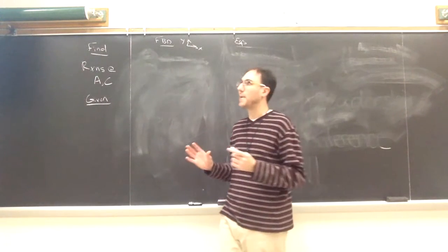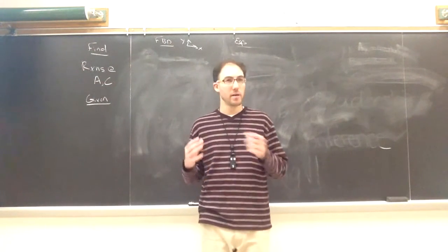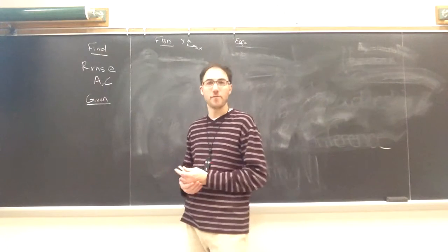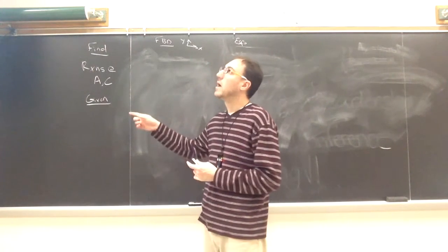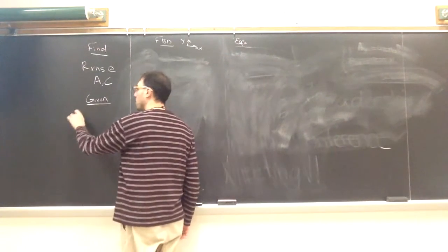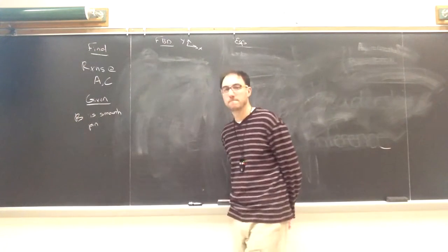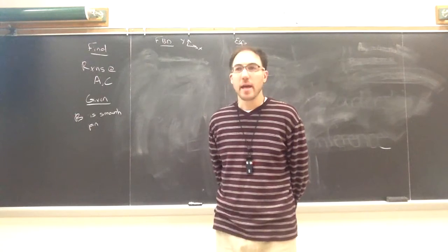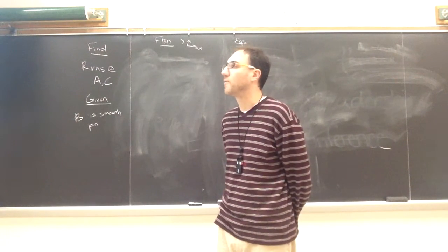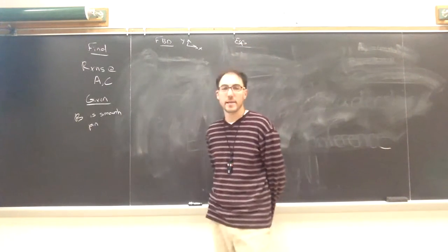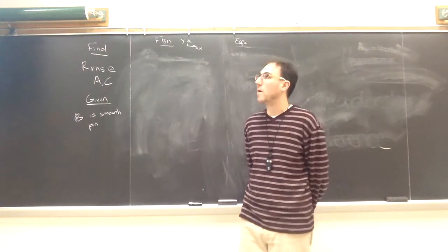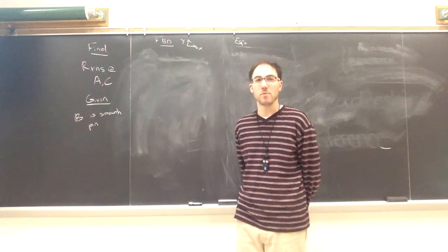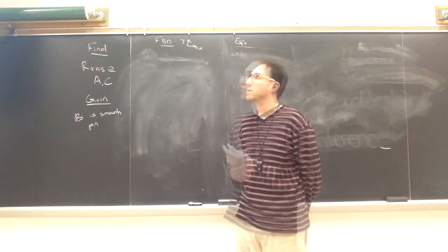So the external free body diagram would only give us 3 equations, not enough for all of the reactions we're looking for. And we're told that B is a smooth pin. First thing we can try to do is see if we have any 2 force members in the picture. So here, are either of the 2 members 2 force members? The answer should be no.